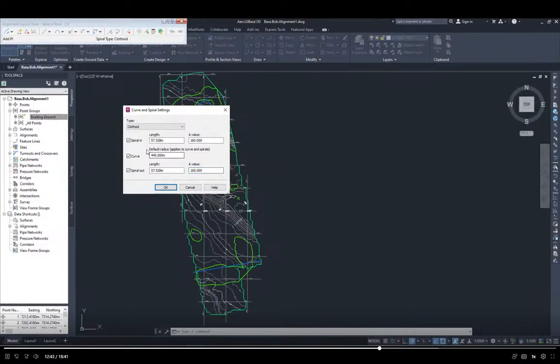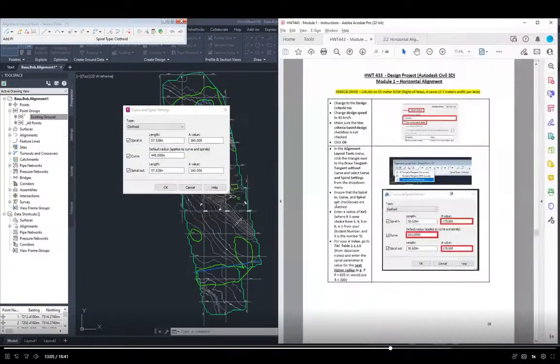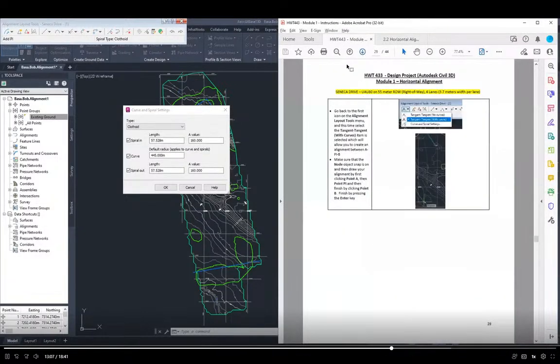The radius you chose on the criteria in the document, you have to go to your spiral parameters 006 page and choose your appropriate A value. Choose a radius that's bigger. It'll provide a longer length of spiral, and that's what we want to do here. Okay. So once we are now here, we're going to go forward. Now we're going to hit OK here.